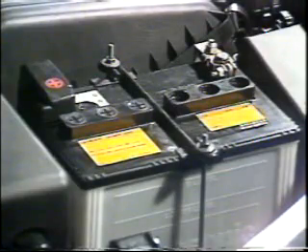Another typical fault is overcharging of the battery. If the battery is overcharged, a lot of bubbles will be seen in the electrolyte, and the electrolyte will decrease considerably, and the light bulbs and fuses will not last long.